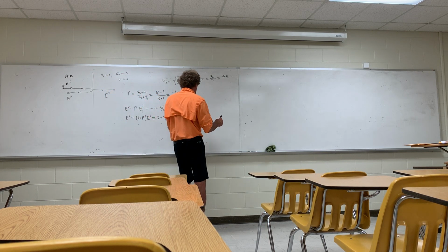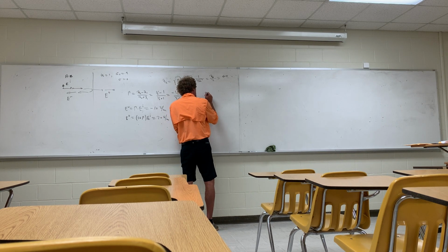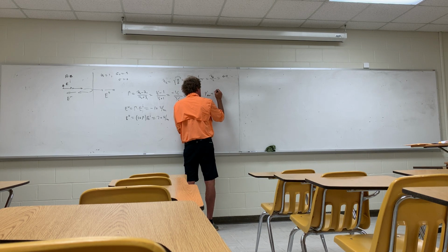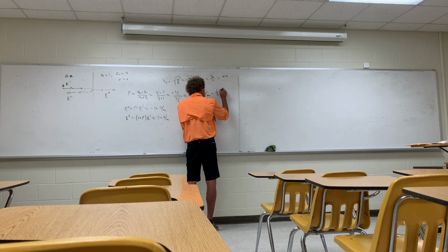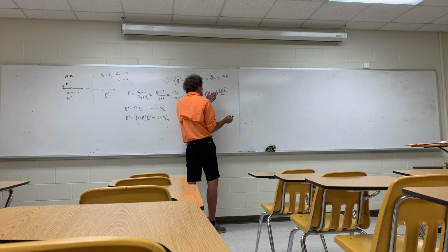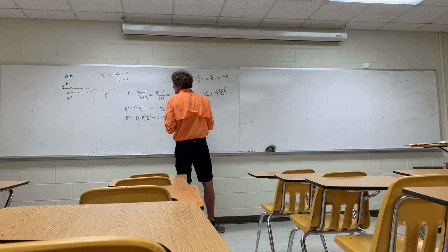Then the next thing they want is the power. I think, did they want the incident power? Did I ask for them? Yes. You get that. So that's going to be simply 1/2 times the magnitude of the E field incident squared over eta naught. And the incident field is 30 volts per meter.